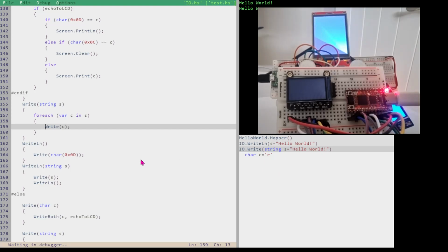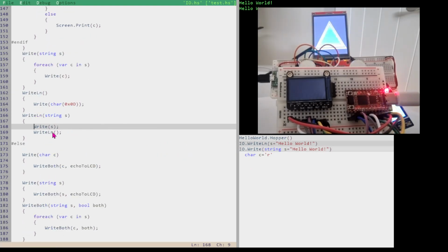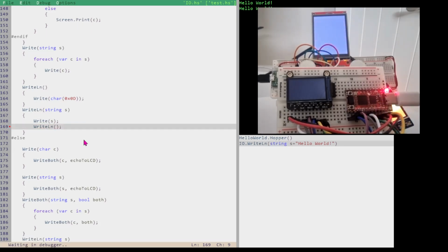So unlike the Arduino environment or the MicroPython environment, this is a full debugging experience without any extra wiring or debug hardware. Via your serial port, you have a full debugger and you can step through. And you can put breakpoints in as well. And you can double click on everything that you think you should be able to double click. So we can put a breakpoint over there when we hit the writeLin, and then hit F5 and it'll go until it gets to our breakpoint. It's stuck on our breakpoint.